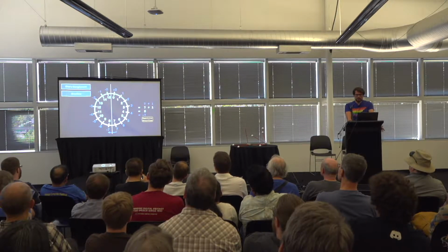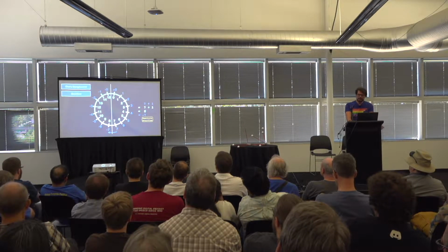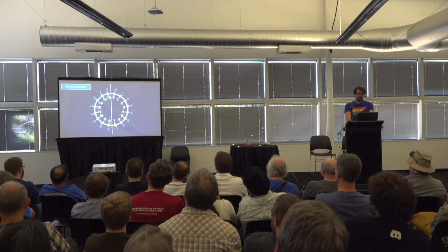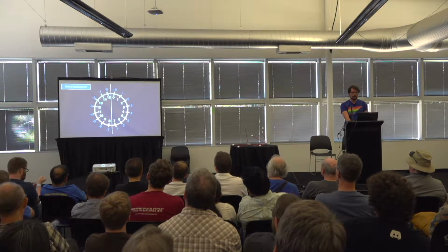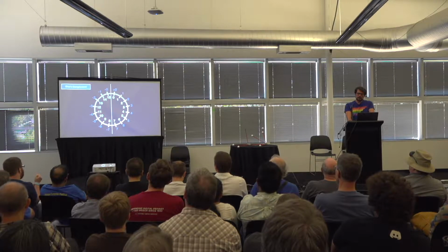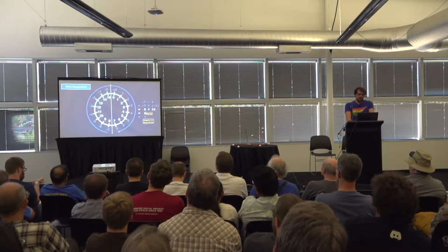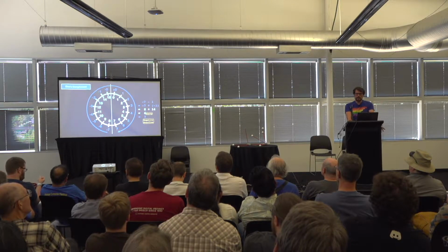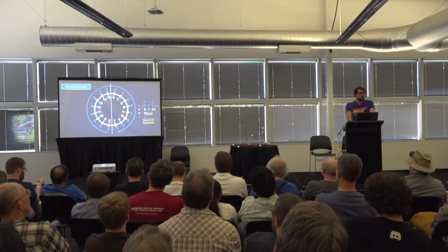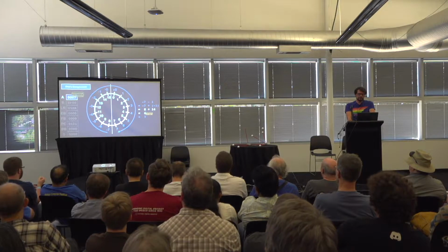An overflow means that the signed result does not fit into the number space. Signed 7 plus 1 would result in signed -7, which is incorrect. The same happens when overshooting negative numbers. After applying the end-around carry, the result of signed 7, in this case, is incorrect. The CPU detects this and flags the result. The accumulator has an extra bit to record the information about the overflow. We will call it V.